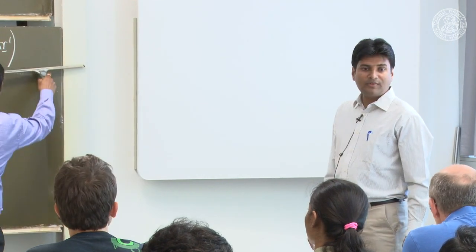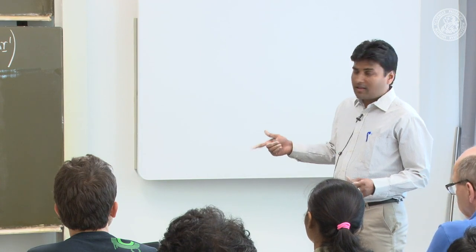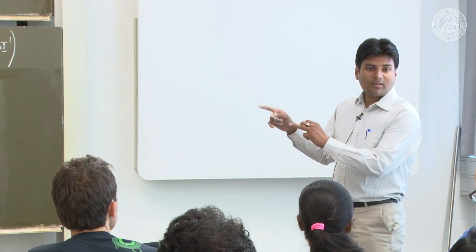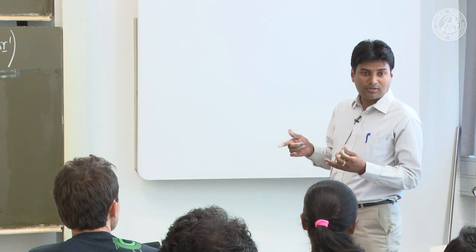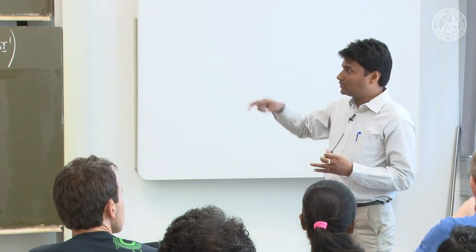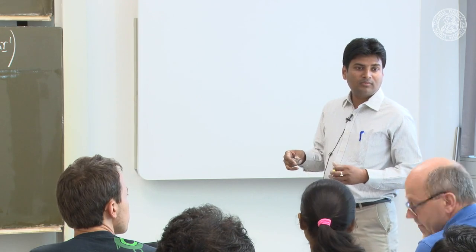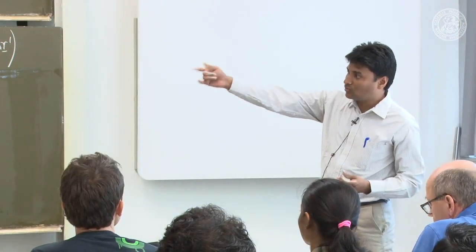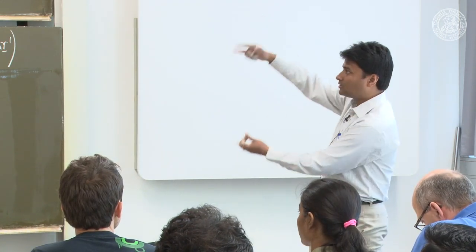See, our final motivation is just to show that the derivatives give us forces and moments, and we have to work out so much. But this is also useful at many other places. For example, when you work out the finite element simulation or finite element solution of this elastic rod, you have to get the weak form, take the variation of the weak form. When you take the variation, you will have to take the variation of rotation, you have to take variation of the curvature. So you have to understand these things.